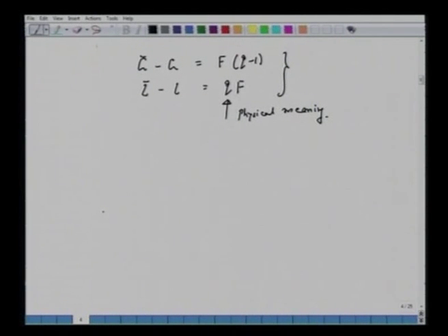Let's say that now we have an equation which is in terms of Q, quality of the feed, which is given to us. So we can write down these expressions. All right. Now let's consider again two operating lines. So right now we want to draw this Q line. Okay, we will see what is Q line.